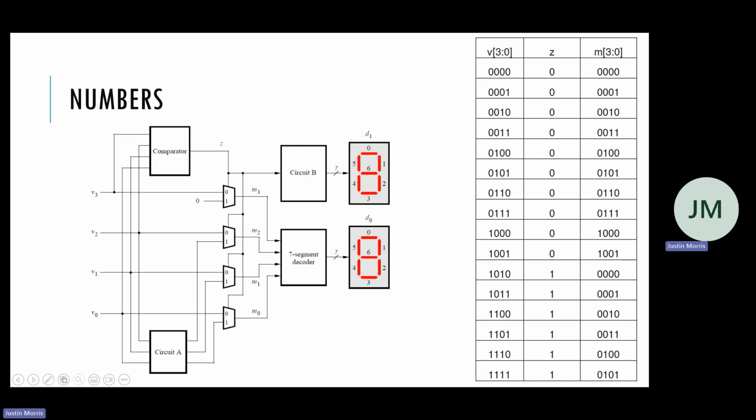I need to create some combinational logic to decipher, from these 4 bits, what my display should be showing. You will be given this piece, which is what we were implementing before: from just the 4 bits, and only expecting 1 digit out of it, which of the 7 segments need to be activated.